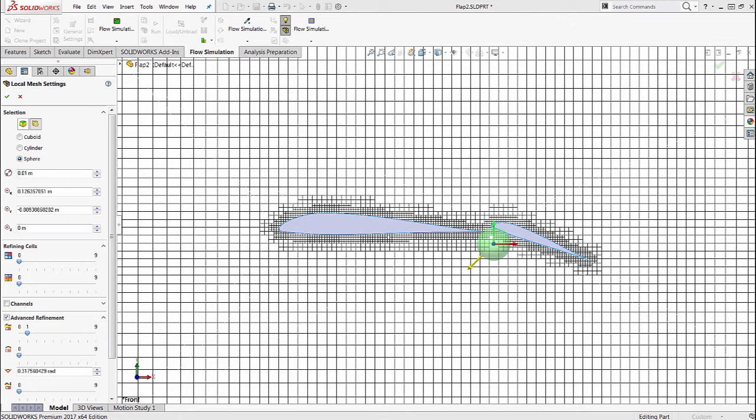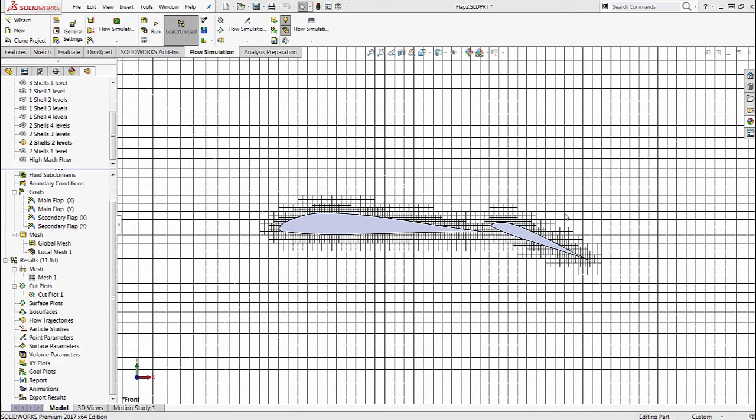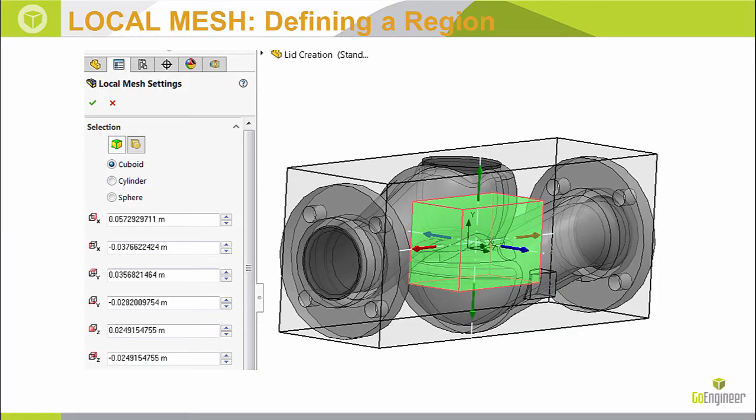All right. So once again, wrapping up in meshing, it is always recommended to have a local mesh with a smaller size defined for the critical areas, but keep the coarse mesh size for the other regions that are not that important. And this will help exponentially reduce your solve time, but at the same time give you accurate results for your models.